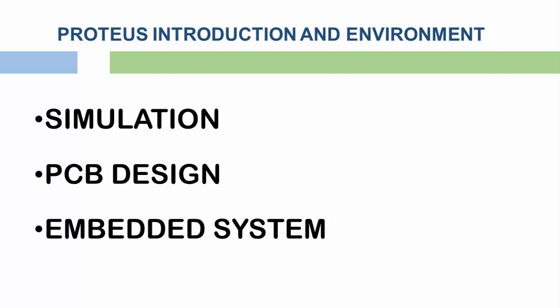So, when you have an idea for an electronic circuit, first design the simulation with PROTEUS. If it works fine, then design the circuit on a veroboard or breadboard. If it also works fine, then design the PCB with PROTEUS ARES.